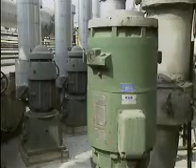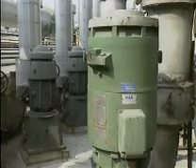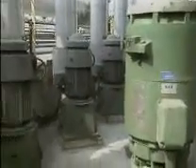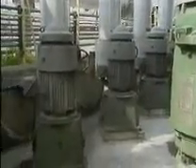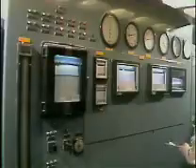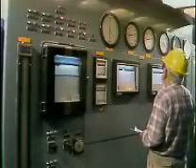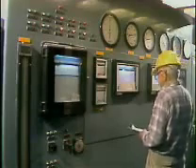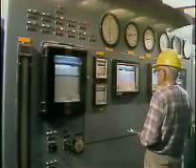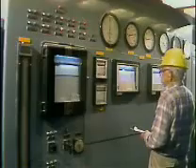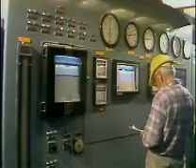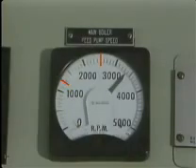However, the operating speed of some machinery cannot be controlled. In these cases, the machinery is normally designed to operate at speeds other than the critical speeds of its components. On machinery for which the operating speed can be controlled, how do you suppose safe operating speeds are normally determined? Safe operating speeds are normally specified by the manufacturer. In addition, operators are usually taught to avoid operating rotating equipment near any of its critical speeds.